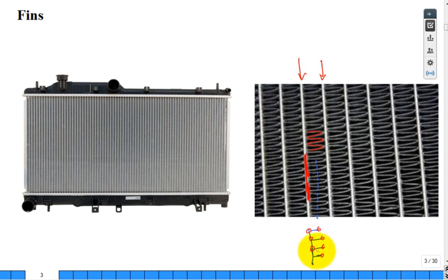Do I need to use a corrected length for that? No, because it truly is symmetrical. Hence, it's effectively an insulated tip boundary condition. Because, you know, this side on there looks just like that side.